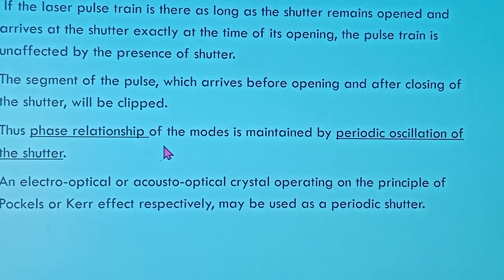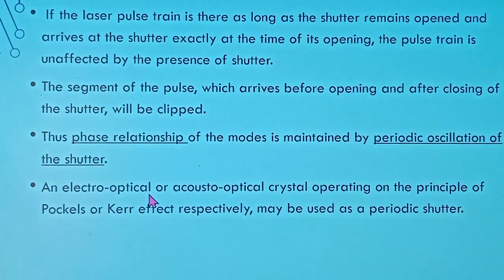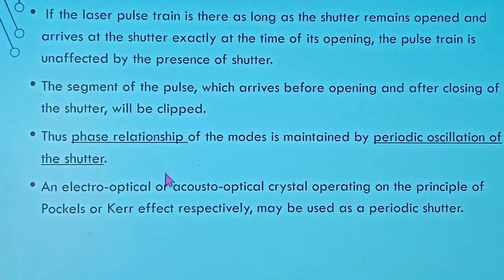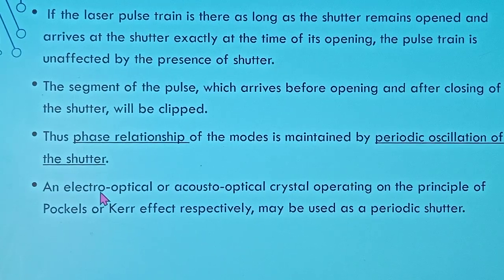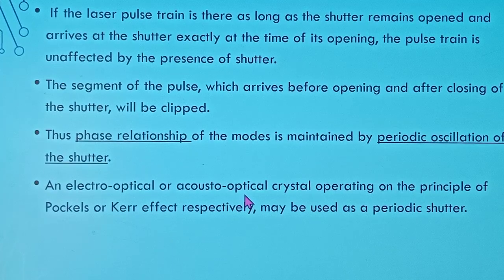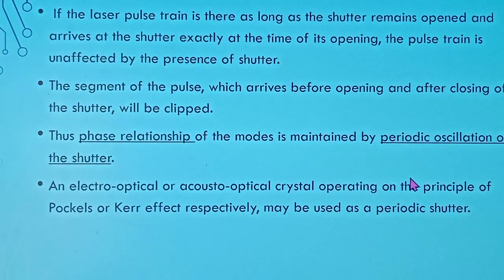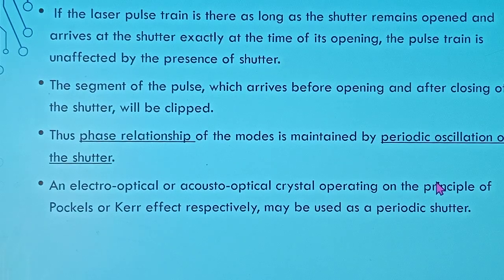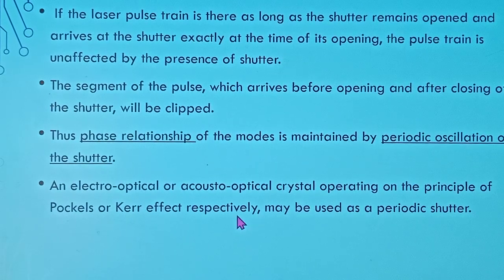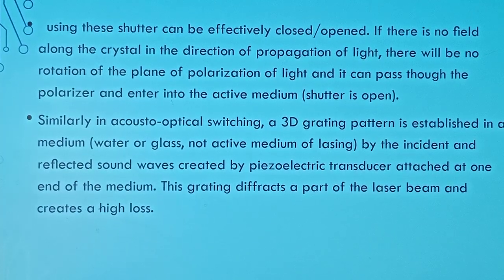And there are various shutters which are available. The most common ones are the electro-optical shutter or the acousto-optical shutter. Now they work on the principle of the Pockels effect or Kerr effect, and that we'll see shortly.